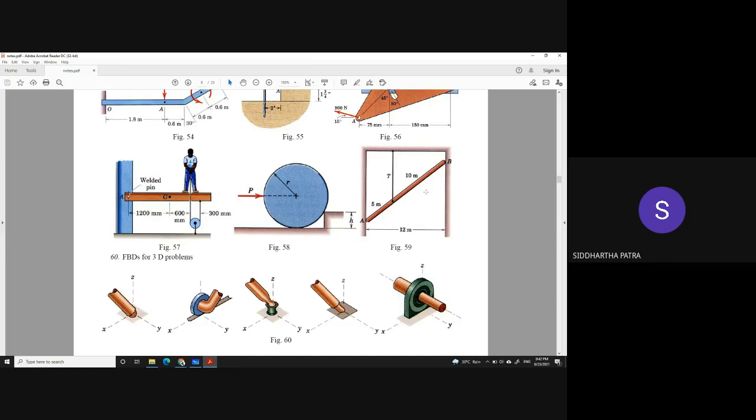That also has a reason: the designer anticipated that with all the other kinds of loads, the shaft would try to move in positive y, and that had to be prevented by making it wider on the left hand side. The diagram could be confusing, but that was in the mind of the designer.